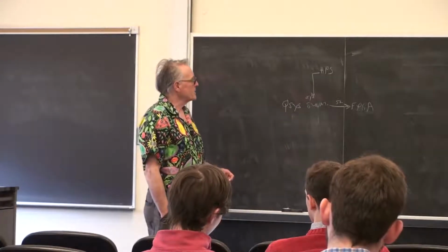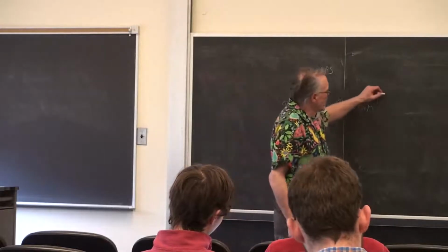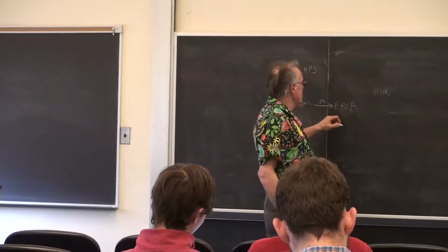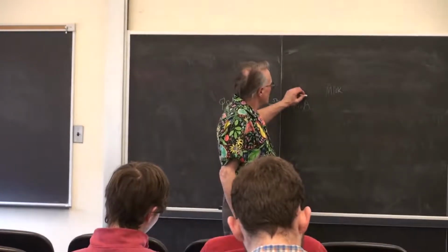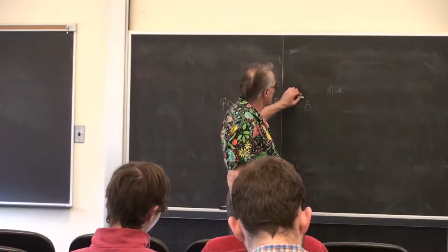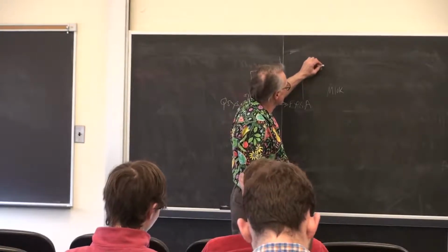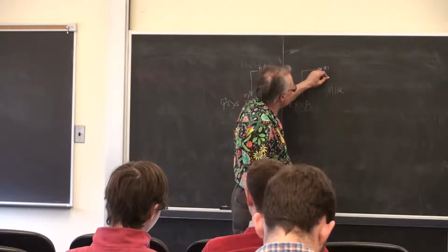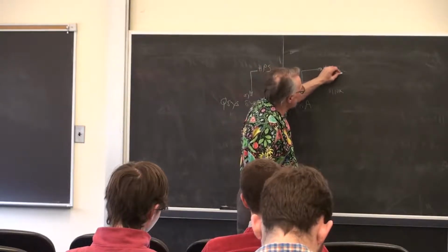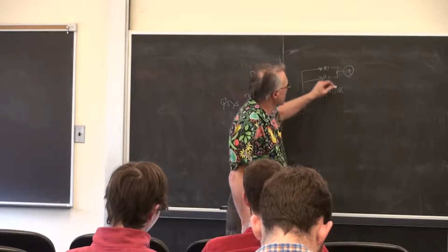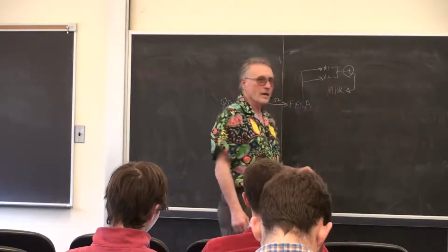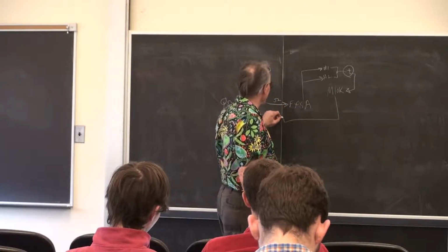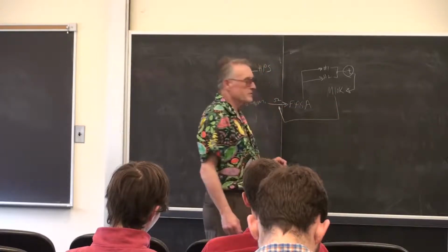So what I did then, on the FPGA side, was to instantiate an M10K block. Read two numbers out of here, first number, second number, do a floating point add on those, an F add, store it into the M10K block, and then write the M10K block back over to the SRAM.